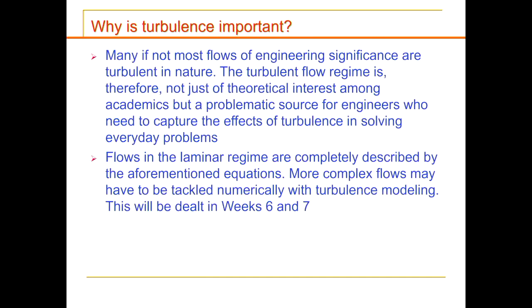So turbulence. Now, why are we concerned about turbulence? Why so much fuss about trying to understand turbulence? Almost all industrial problems or engine problems are turbulent. Why? Because we are dealing with high Reynolds number flows, unfortunately. Even the airflow in this room is turbulent. So turbulence is important, and we need to know how to solve turbulent flow in a CFD context.